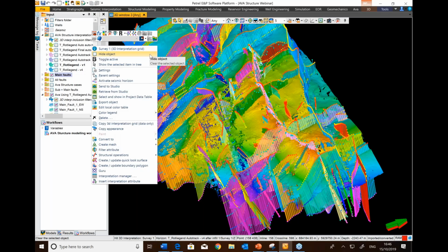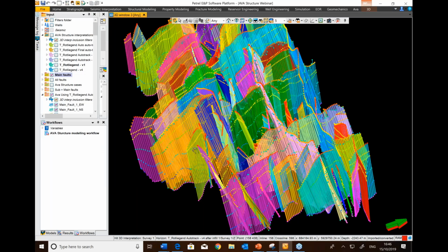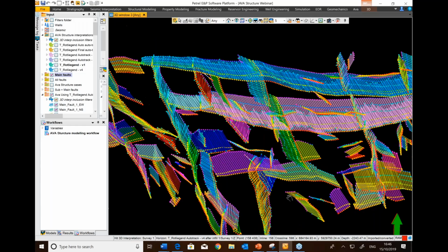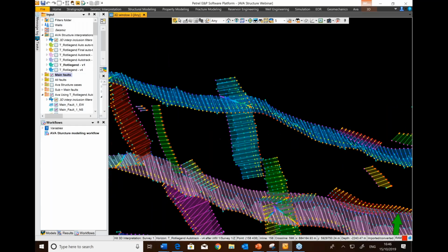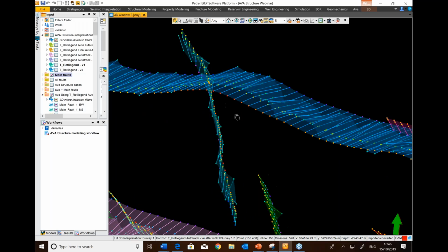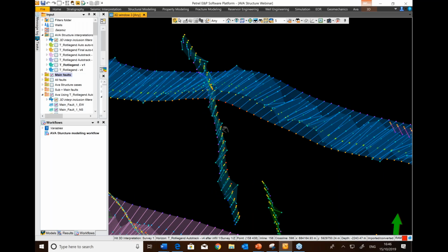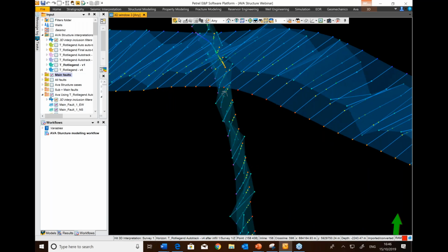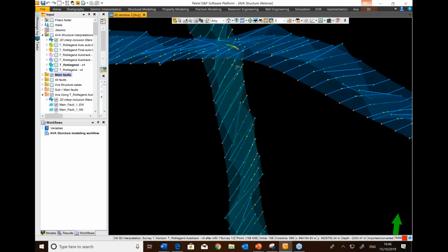So what we're doing here is we're taking that initial fault interpretation, we're applying the fault tip extensions, connecting up the faults appropriately, and then we're also applying some smoothing, essentially to make them fit for purpose to go through to things like the structural modeling workflows. So automatically, you can see very quickly that I've generated this connected fault network with my fault tip extensions that's fit to go forward to modeling.